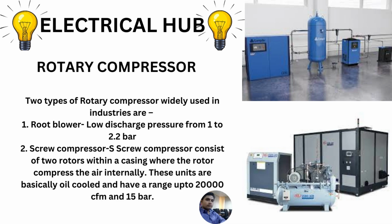Root blowers have low discharge pressure from 1 to 2.2 bar, but the screw compressor consists of two rotors within a casing where the rotors compress the air internally and it is also cooled internally, so they have a range up to 20,000 cfm, that is cubic feet per minute, and pressure up to 15 bar.